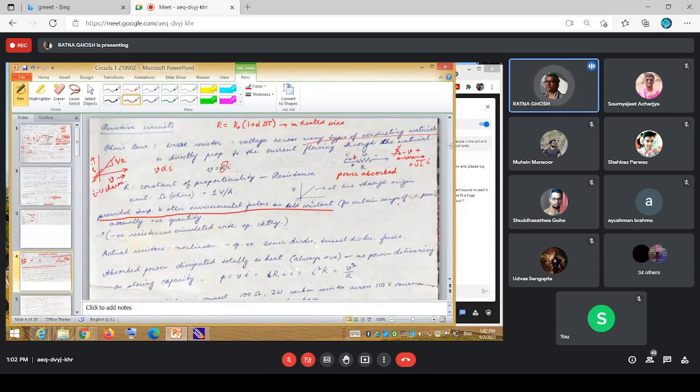So what we actually have are ratings of the resistances. Any of these passive elements have ratings. In the ratings, you will have the value of the particular resistance or the inductance or the voltage limit. Along with that, there will be a power rating also. How much power can that element tolerate or absorb? How much heating can it tolerate? That is the indication of that. Does anybody have an idea what the power rating of the usual lab resistances is?